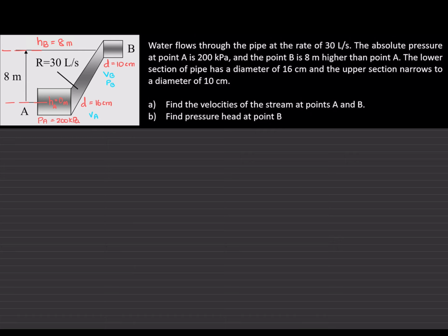Now we know that the flow in this water is a streamline flow because all questions that we are dealing with in here are streamline flow. And we know the formula for flow rate as well. Flow rate equals velocity times area. In the question as such, we assume that the mass flow rate at the inlet is same as the mass flow rate at the outlet.